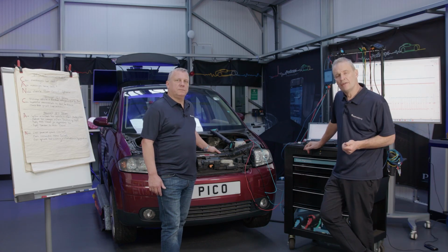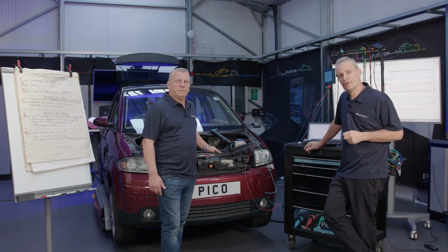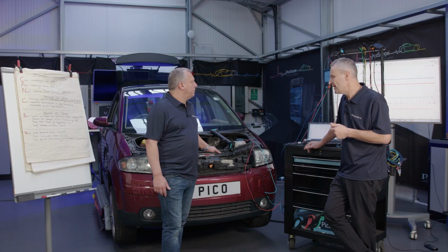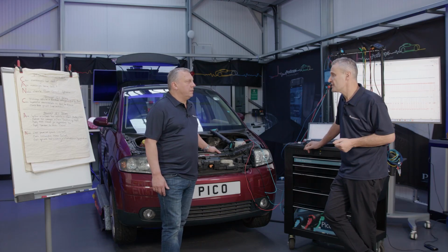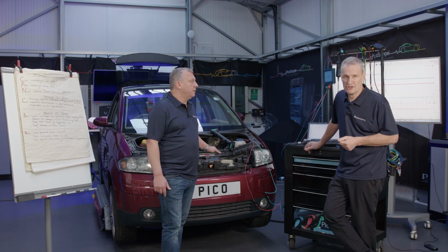We want to capture the recessive state. This is where we are sort of ignition off and power down. So CAN will go through a kind of shutdown procedure. In my experience, it varies. I mean, absolutely, from car to car. It can be up to 20 minutes or more. So it's a long time to wait.